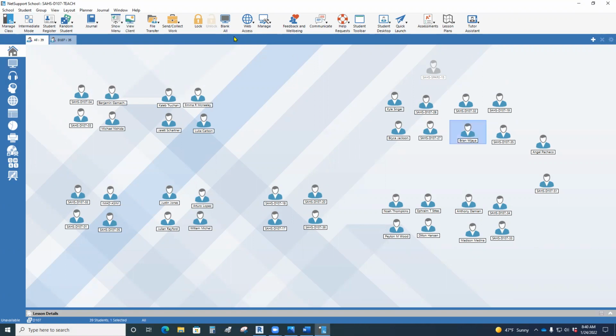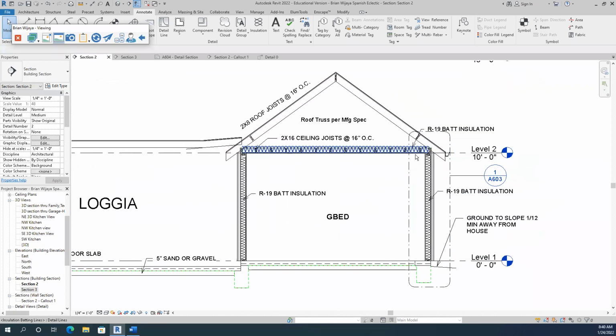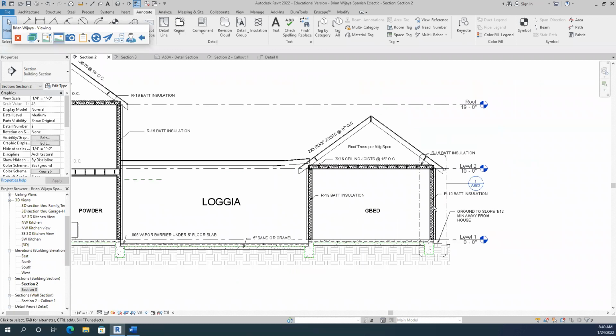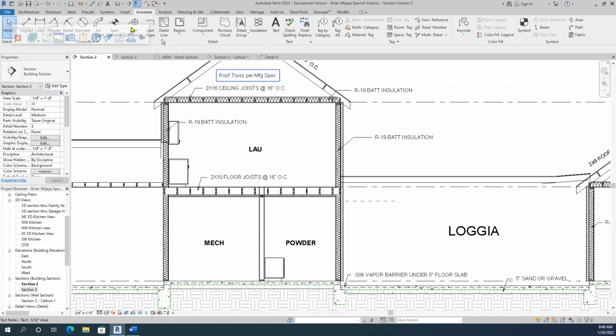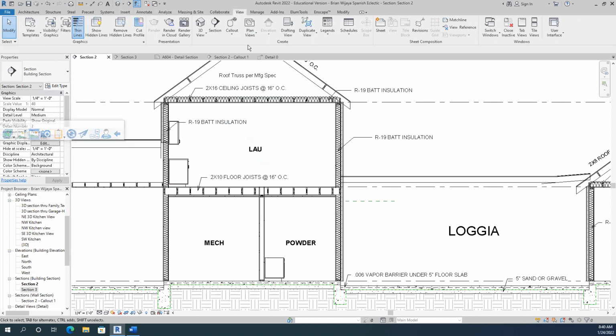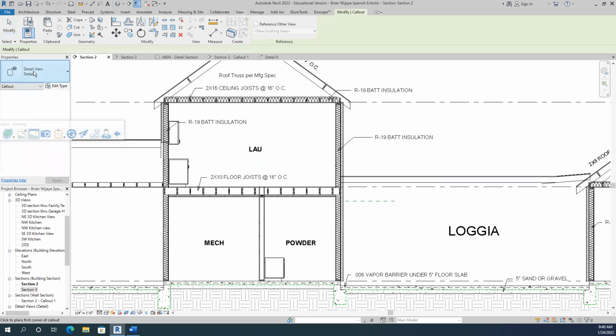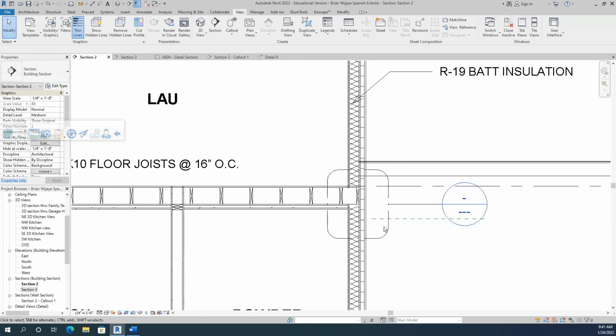Okay, Brian. Let's see. View. Yeah, okay. Yep. That's okay. No, we're just gonna do it somewhere else. So what you're gonna do is just do it over here. Yep, it's not a problem. It doesn't have to come from the original wall section. So do it like this. View, call out, rectangle, detail, and then just do it, like right there. And it's the same rules and all that stuff. Yep.